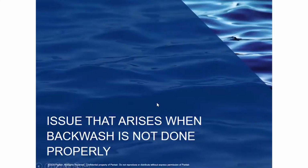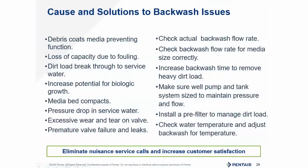So, issues that arise when you don't backwash your carbon properly. Well, debris is coating the media, preventing function. You have a loss of capacity due to that following. Dirt load might break through to surface, come out dirty. Increased potential for biological growth in the tank. With activated carbon, depending on the bacteria, that may not be a bad thing. So we do use bacteria with activated carbon in special cases. We don't want the wild stuff though.